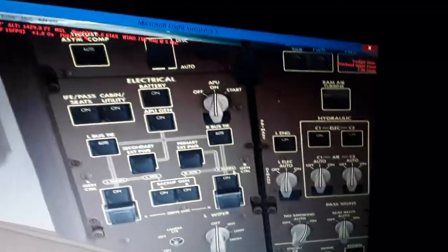We have the left engine driven electromagnetic alternator, 120,000 watts, alternating at 400 Hz frequency, 120 to 200 volts. Its electromagnetic alternator is bipolar, north and south pole, with electromagnetic induction to create this alternating current. 400 Hz frequency, 120,000 watts, left engine and right engine.